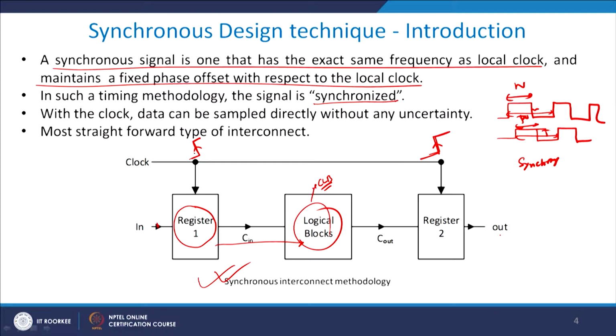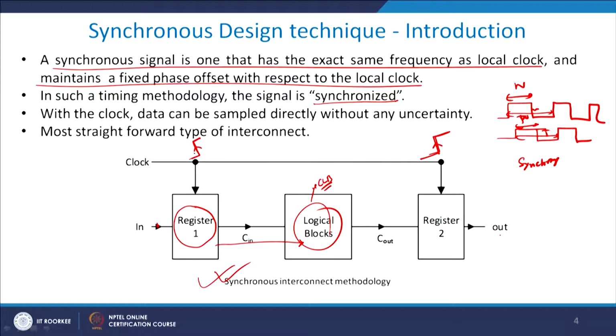If I assume that the logical block has 0 delay, then I would expect that the insertion of data at register 1 and the output at register 2 are in exactly the same time domain, provided the delay is 0 for the combinational logical block. In reality, that is not true, and therefore that gives you a constraint on the total time period of the external clock for a sequential logic.